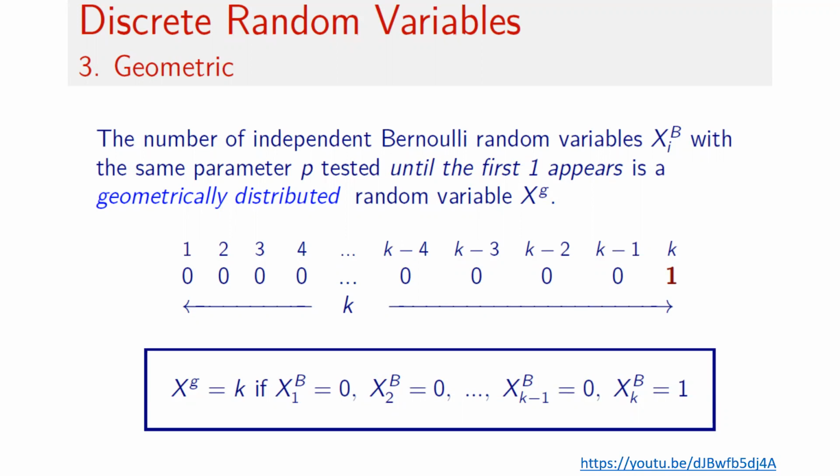Here is how many throws of the coin I have to wait until I obtain heads. If we translate the knowledge to our case, a manufacturing system, we can say how many discrete times have to pass until the machine fails. So we can use this geometric distribution to know the probability of when a machine will fail.